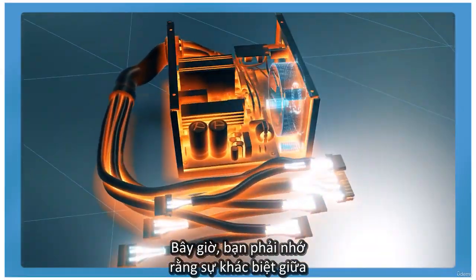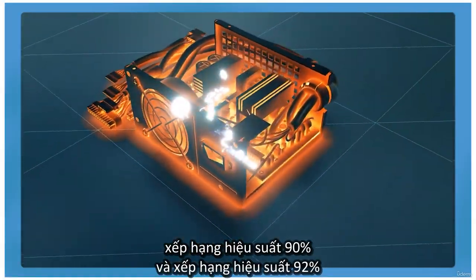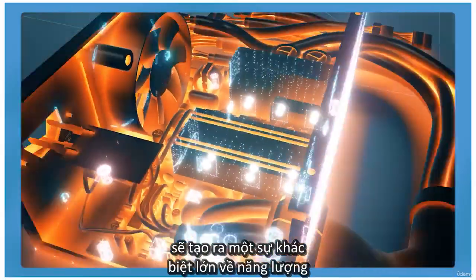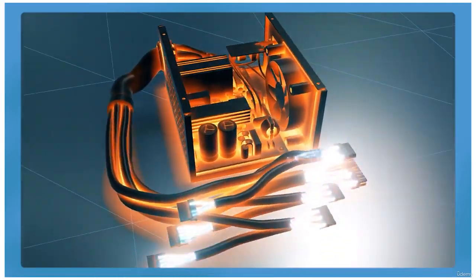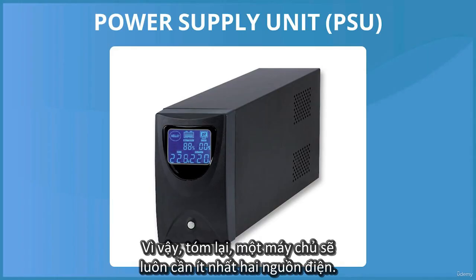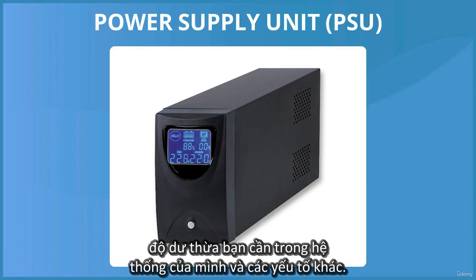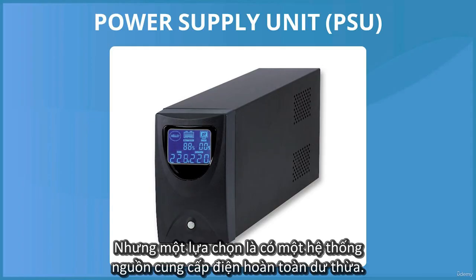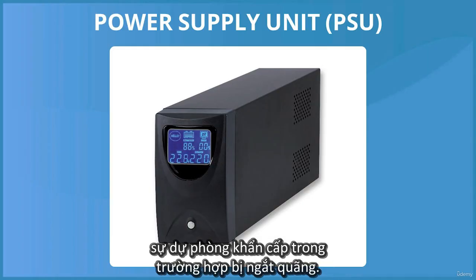Now, you do have to remember that the difference between a 90% efficiency rating and a 92% efficiency rating is going to make a massive difference in terms of energy utilized within large-scale data centers. All right. So in short, a server will always need at least 2 power supplies. Yeah, there are different modes of operation for this depending on how much redundancy you need in your system and other factors, but one option is to have a fully redundant power supply system. So that means that one PSU is always switched off, and there's an emergency fallback in case of downtime.